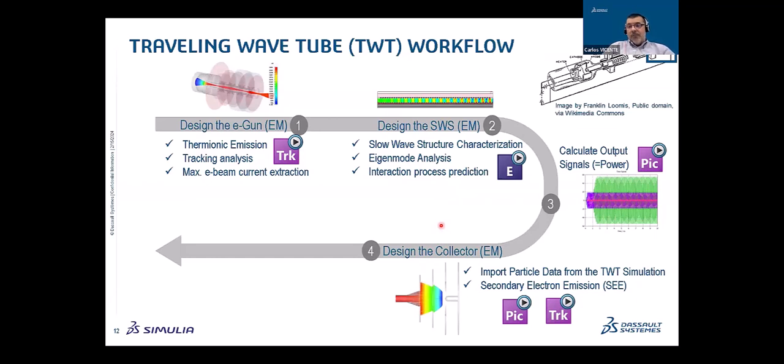In this design, you have to ensure typically that electrons are absorbed on the surface, and typically what you try to do is to do this in a kind of homogeneous way, just trying to avoid hot spots, places where you have a huge current coming from electrons, because many electrons are impacting on a particular part. Of course, to do that, we also need to consider the properties of electrons impacting on the walls, the secondary electron emission, just to check whether more electrons will be released.